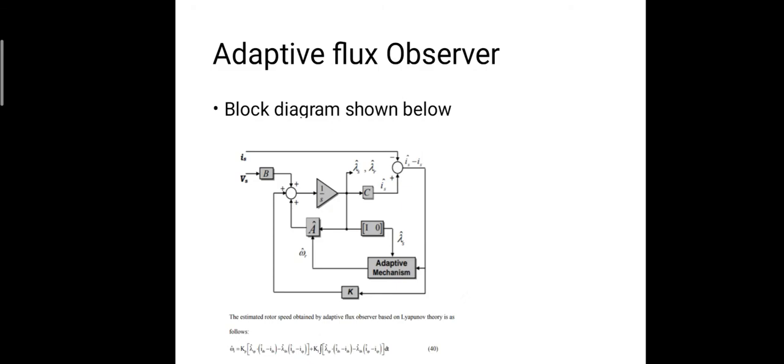The feedback gain K is chosen to ensure global stability and robust dynamic performance of the closed loop observer. A pole placement approach is employed, and the choice of desired pole locations is usually a compromise between achieving faster response and retaining high robustness. The adaptation gains are selected by trial and error or by considering the root locus of the linearized model. These methods based on machine models stated earlier deliver accurate and robust speed estimation performance. These methods may achieve robustness and high performance with parameter variation.